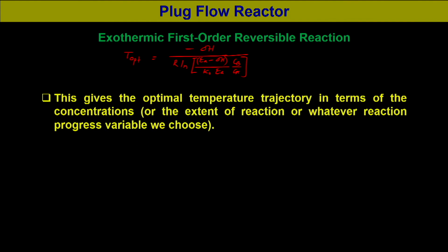This expression gives the optimum temperature trajectories in terms of the concentration or the extent of reaction or whatever reaction progression variable we choose. So, this will give the optimum temperature, how it will progress in a plug flow reactor.